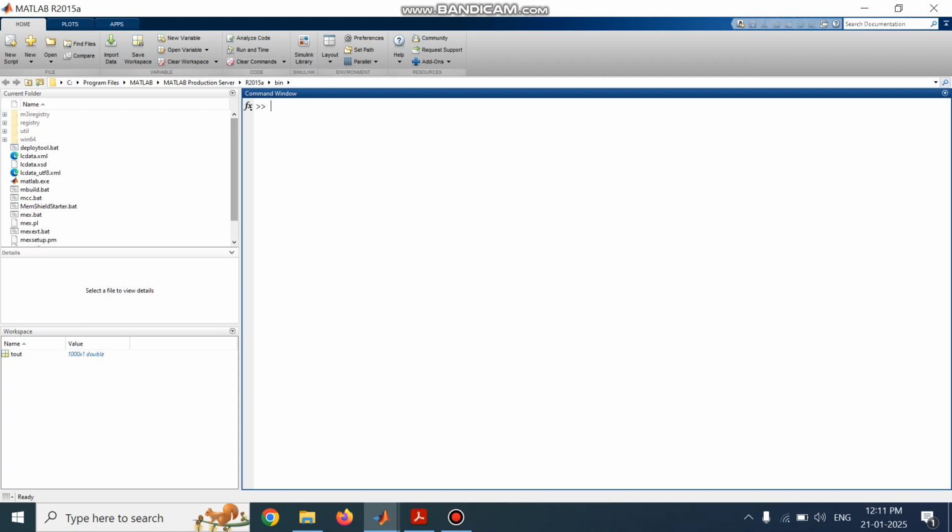So 0 0, 0 1, 1 0 and 1 1. So 4 different symbols are possible here. Compared to binary phase shift keying, this QPSK is a bandwidth efficient method.